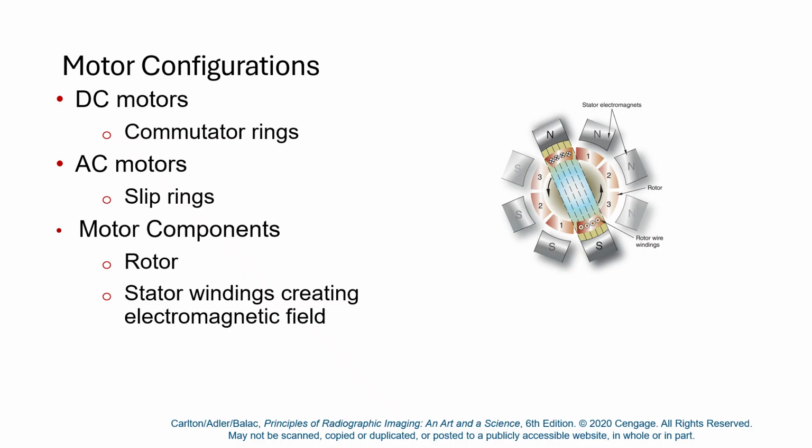The rotor in an induction motor is meant to experience the changing magnetic field. So Michael Faraday would say that the rotor has an induced current, and then Lenz would say that induced current will create a magnetic field in opposition to the rotating magnetic field. And so there will be a repulsion, but since the magnetic field is rotating, the repulsive force is actually a torque that spins the current carrying rotor.